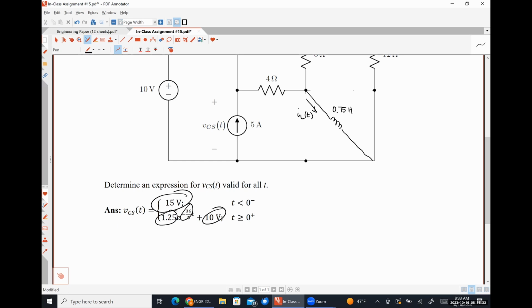So think about this as the positive polarity terminal for the time varying voltage you're measuring. This is the negative polarity terminal. Oscilloscope probes are only used for measuring things. If you hook it up to your function generator, it will not work. This is what connects your oscilloscope to your circuit so that you can see what is going on.